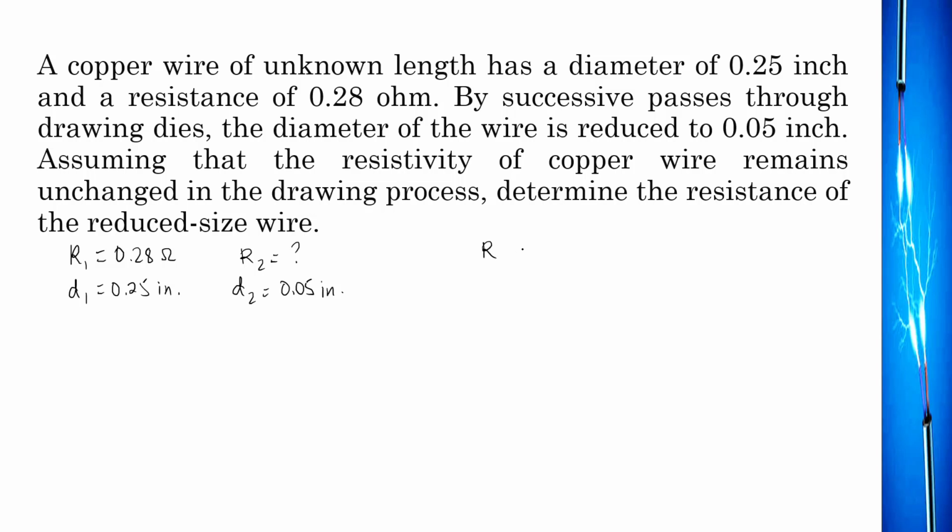So, according to the law, when it comes to the drawing process, we can have this relationship that the resistance is inversely proportional to the square of the area. Take note po, dumaan po ito sa drawing process, so hindi natin pwedeng i-disregard yung square dito, kasi we are talking about drawing process. Since the given is in terms of diameter, we can also say that the resistance is inversely proportional to the fourth power of the diameter.